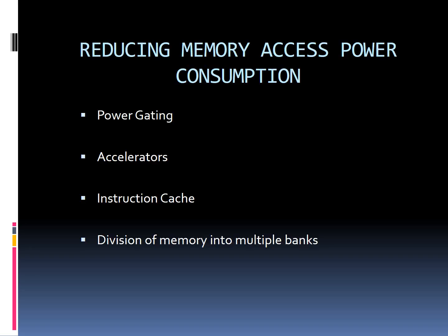Splitting into larger banks, on the other hand, results in increased leakage power. So based on the expected average access rate of the memory, the bank configurations such as the size and the number of banks to be split up can be chosen optimally.